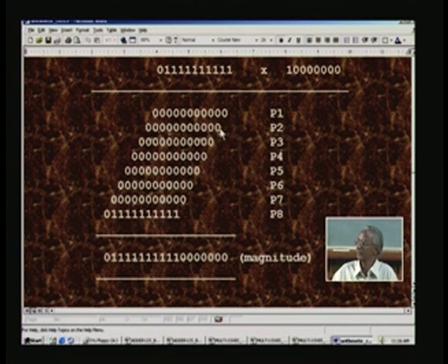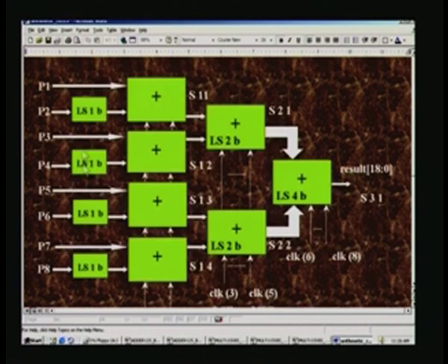So that is precisely what we are doing not only for P2 but also for P4, then P6 as well as P8. So you will see a left shift by 1 bit as far as the first stage of addition is concerned, you can see here. So P2 is left shifted by 1, then only added to P1, and here when this is clock 1, corresponding to this there will be internally a register, and that will register the sum of the LSB alone.